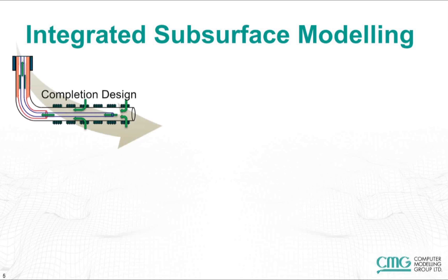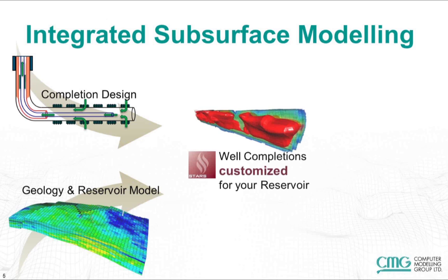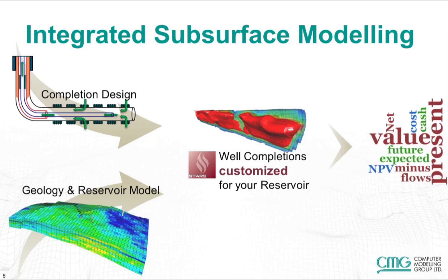Traditionally speaking, the completion design and optimization fell within the domain of the completions engineer or the production engineer. And we often use standalone tools to be able to do this. But we all know the heterogeneous nature of our reservoirs, and geology is something that we cannot change. We have to work around it. Some processes are more sensitive to geology than others, and hence this one-size-fits-all approach doesn't quite work. In STARS, we have a detailed wellbore simulator that is coupled to the reservoir simulator, and thus we're able to customize the well completions for the reservoir, hence maximizing the value of the asset.